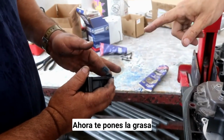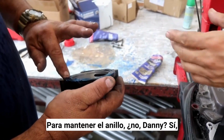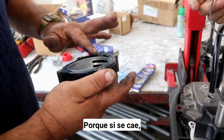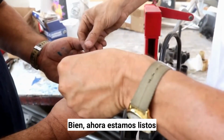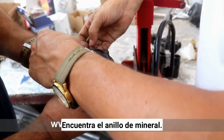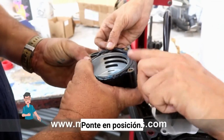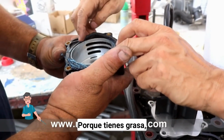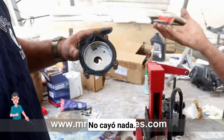And now you apply grease where the O-ring goes, in order to hold the ring, no, Danny? Yes, just so it doesn't fall, because if it falls, you risk the chance of pinching the O-ring. Yeah, that's true. All right, and now we are ready to locate the O-ring in place. And because you have the grease, nothing falls out. That's perfect.